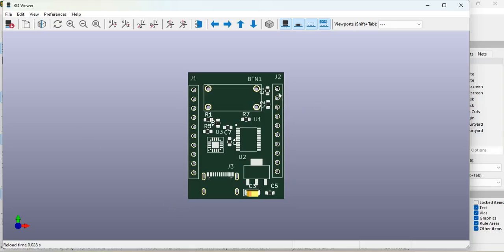So the 3D view here is giving us a very beautiful view of component placement, and you can adjust your components accordingly. And observations you can make here. So C6 is close to this pin, whereas this particular IC decoupling seems to be missing. Even these kind of things you can understand from this view. And you can also see here the J1 and J2 seem to be a little offset from the edge.